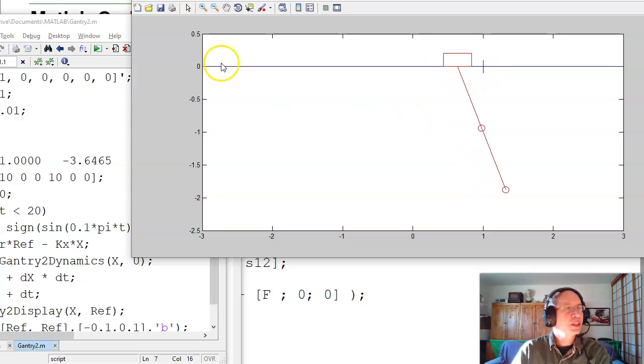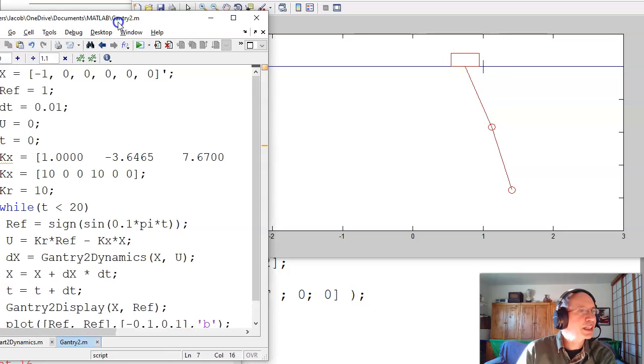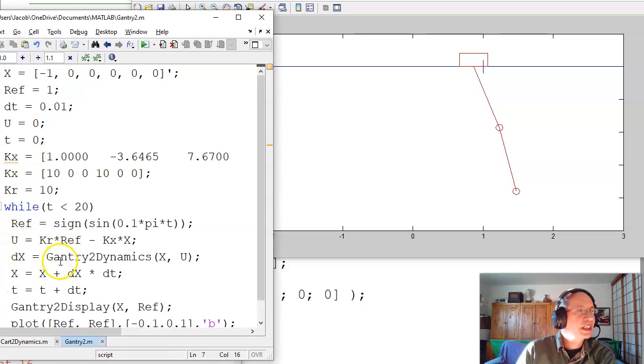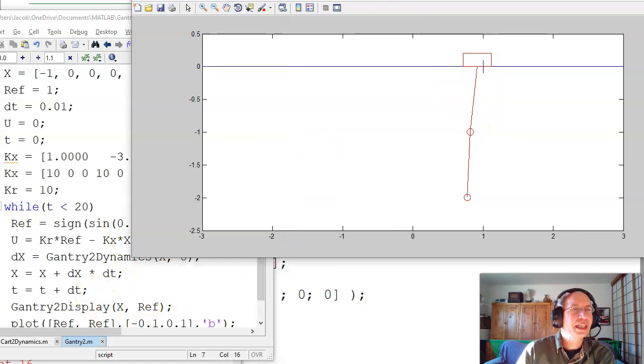But using those same dynamics, you can see what's happening over here. I calculate the input, which is the force on the base, and given the state, I can find the acceleration. Integrate, I get the states. The first 3 states are position, the last 3 states are velocity. Time goes forward 10 milliseconds, repeat, and you get your animation.